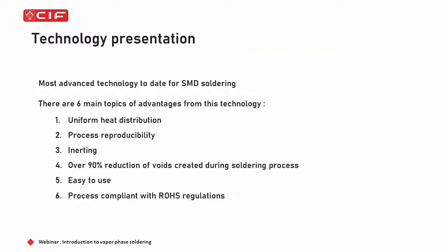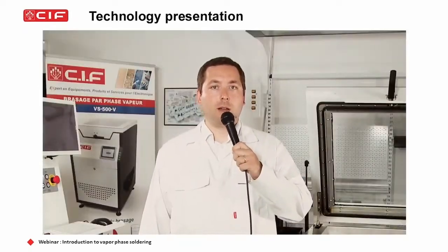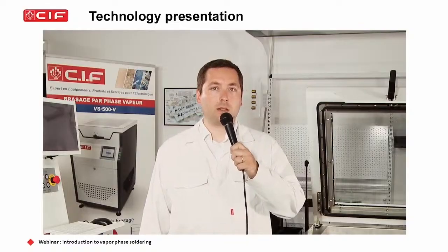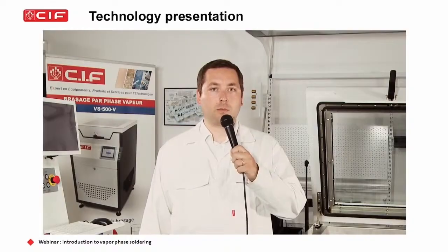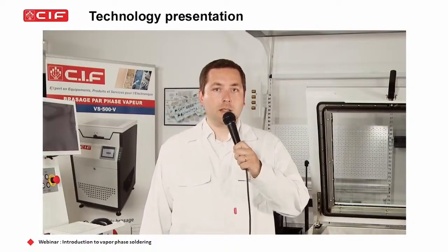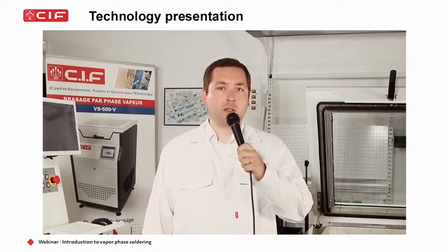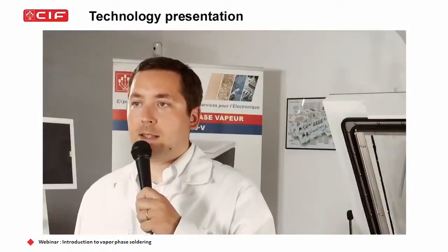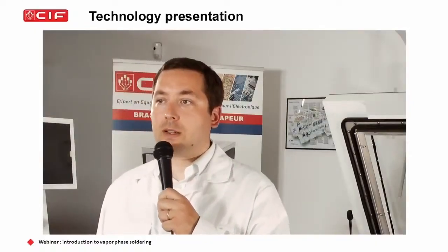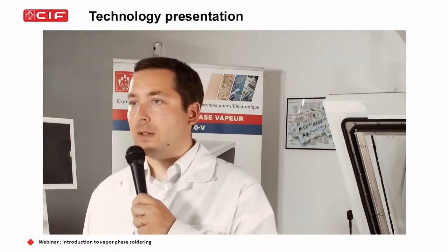So regarding the technology itself, the vapor phase is the utmost technology for soldering. The principle is to use vapor created by a medium. Generally, it is Galden that we use, which is a PFPE chemical product. So the idea is to transfer a uniform heat to the components to be soldered, so PCB, alloys, and package elements.